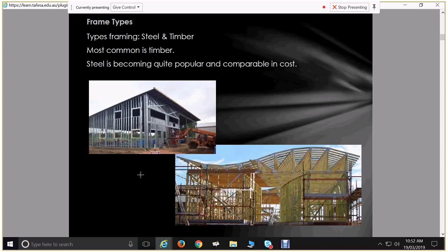But it's a renewable resource. We can keep growing timber. It takes carbon out of the atmosphere. It locks carbon away in that frame. Whereas steel is not renewable. There is a finite amount of iron ore in the ground. That iron ore has to be dug up, cooked with coal and molten, turned into steel. There's a lot of energy input into that, and then that steel gets used. And it doesn't store any carbon. So it has a high embodied energy, but it's not actually giving a net benefit in a carbon reduction sense. So there are a lot of other factors that come into it.